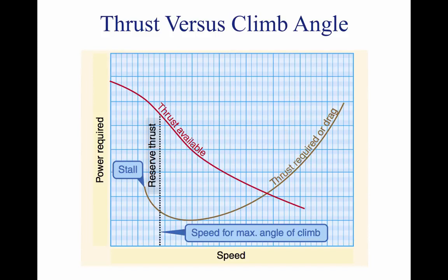A second factor is that the aircraft can trade off its kinetic energy and increase its potential energy by reducing its airspeed. The reduction in airspeed will increase the aircraft's potential energy, thereby also making the aircraft climb. Both terms, power and thrust, are often used in aircraft performance. However, they should not be confused.